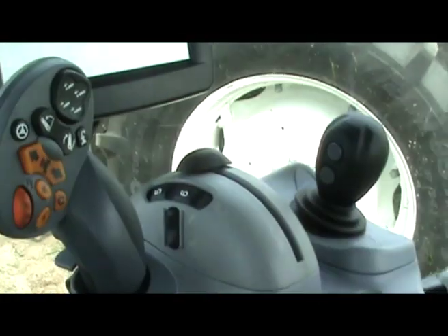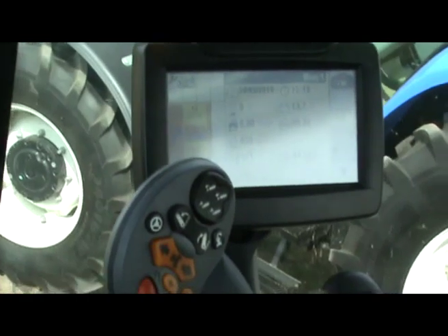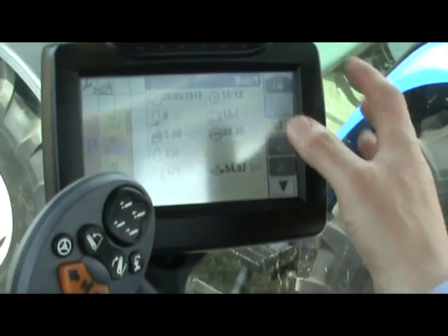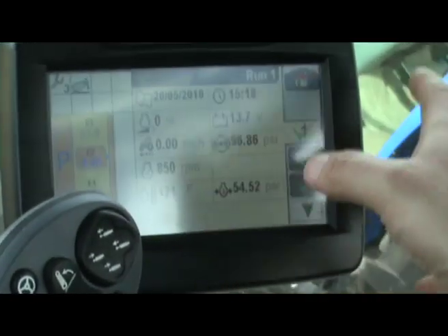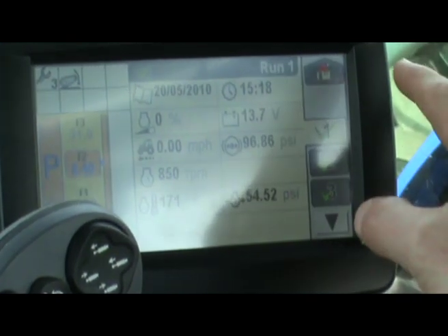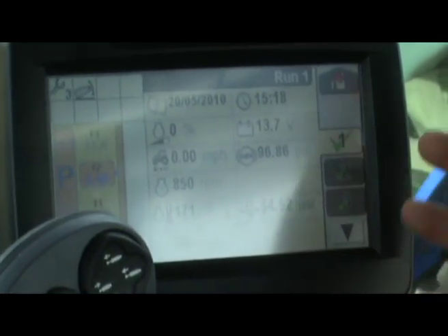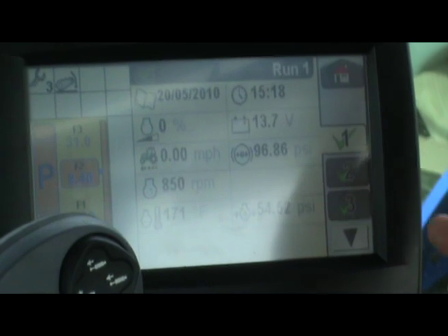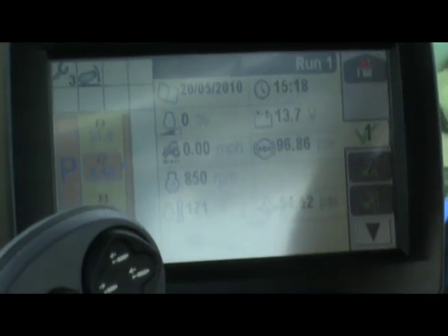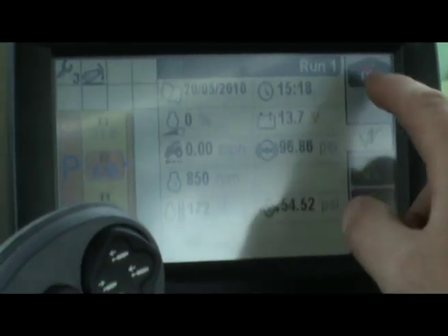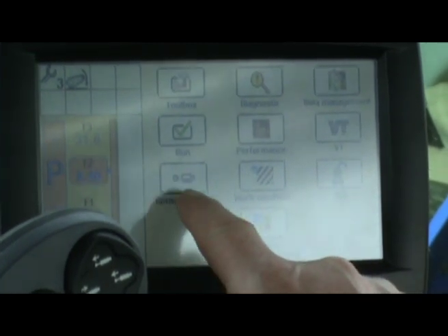And the final piece of Sidewinder is the IntelliView 3 touchscreen. First tractor with a touchscreen in it. Very, very fast method of inputting and controlling the tractor. So for example, if I wanted to change the remote valve flow settings, simply tap the home button. There's a tab for remote valves, tap the remote valve, and there are my 4 rear remotes.